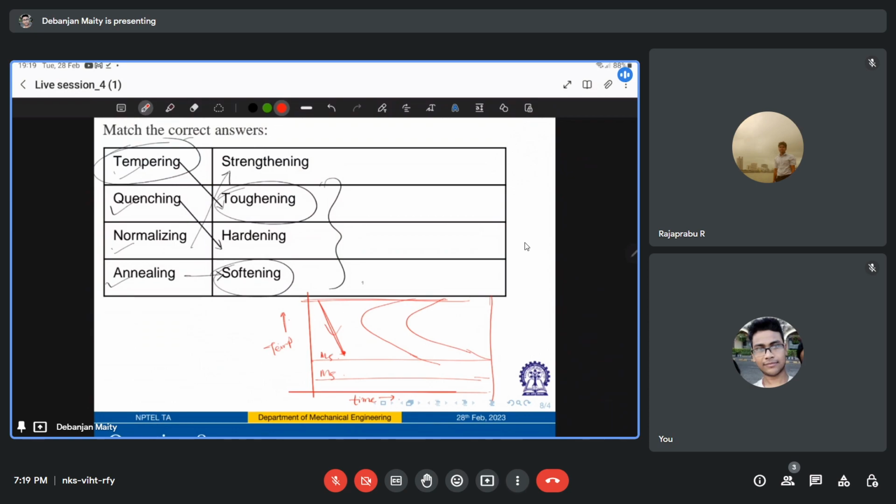And then what you do is you are coming up to this point, then keep it for a prolonged amount of time, and then you end up with some fine bainitic structure, and then you leave it over there to cool in air. That is the algorithm to get an austempered structure, cooling in air. This is what the method follows for heat treatment in austempering.